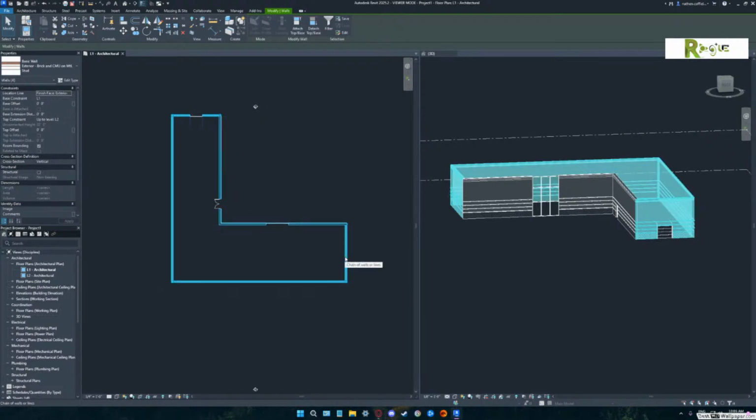All right, so all the walls, let's say there was a wall or 2 that you didn't want picked in there. You would hold your Shift button in. See how it's a minus symbol now? And it would subtract anything from that selection set. So if you clicked on that, it would take that wall out of selection. Does that make sense?